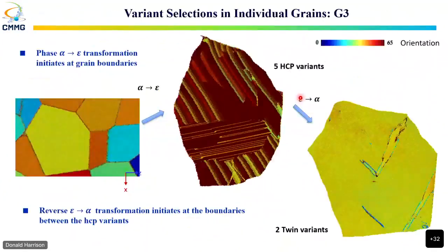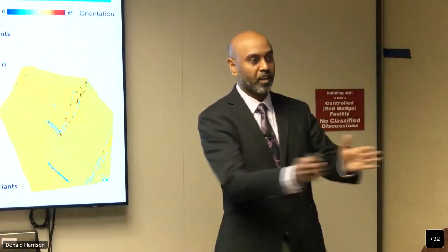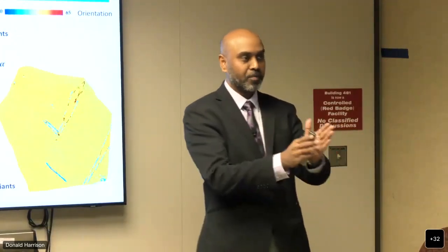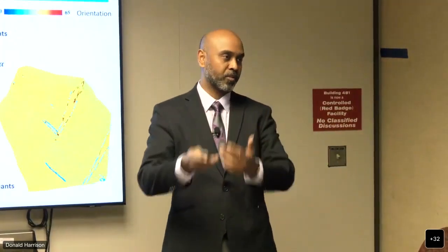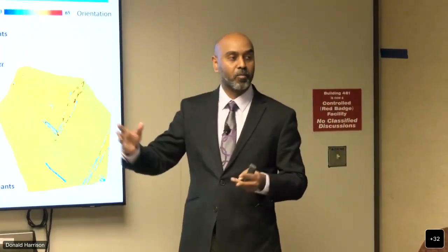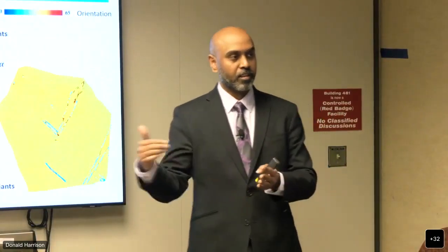Those were similar, but our numbers are slightly less. And I think it's because our plume is allowed to expand completely freely. And if you stop that, then there's going to be a slightly higher pressure, and it'll push the velocities a little bit higher. So that's what we want to validate, because it's difficult to mimic a glass interaction and an epoxy affecting the plume. So we want to calibrate that model to give us the right velocities.